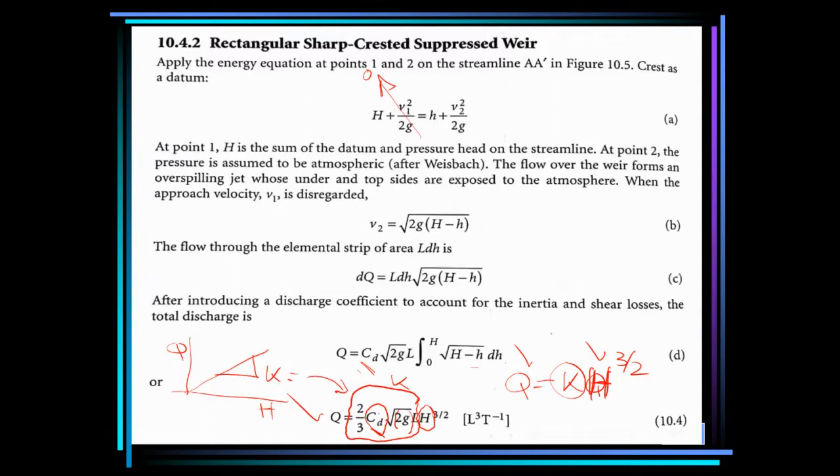So this is one way to find the coefficient of discharge. Flow rate can be carefully controlled in the lab by using a pump, where you can read the value of the flow rate, and the head measurement can be done. This is exactly what we are going to do today in the lab, and then at the end we can find Cd.